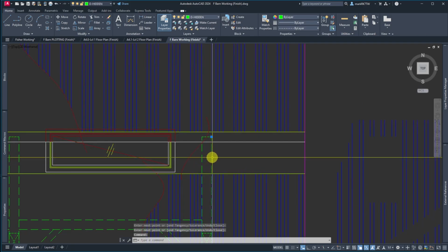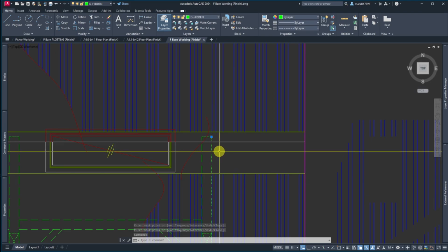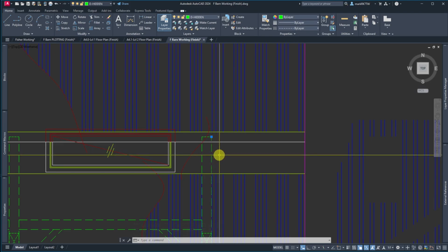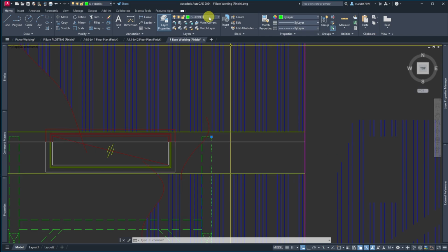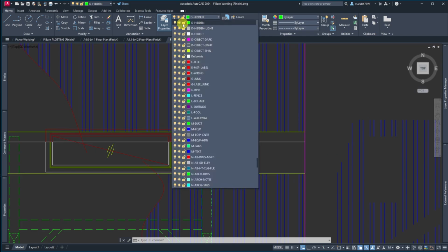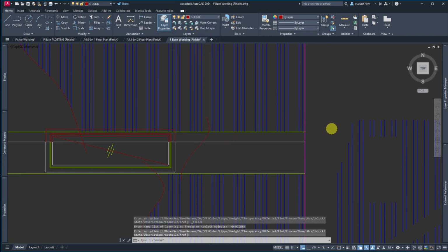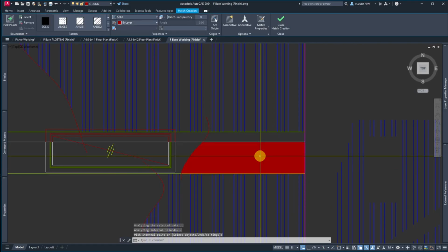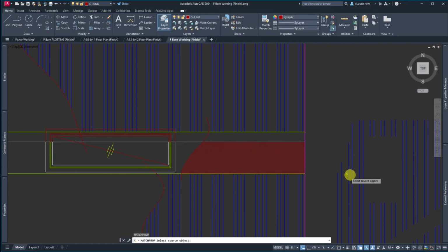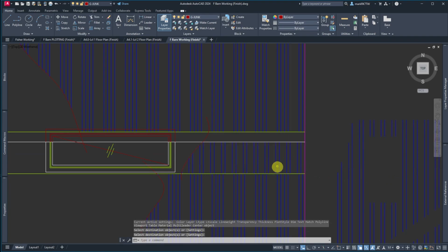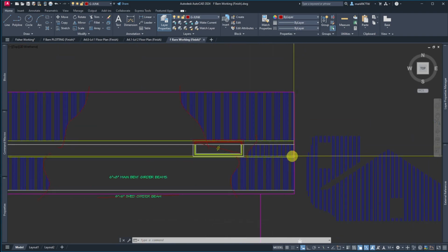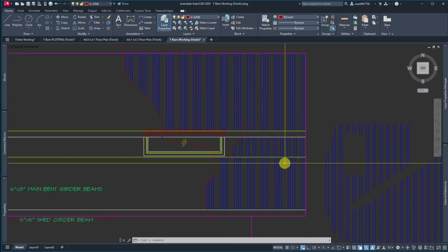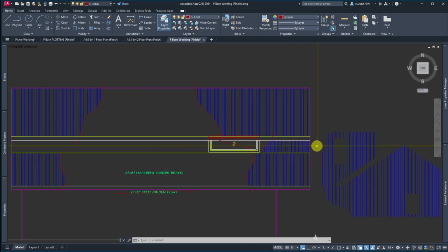That's de-hidden. And if I want to make it the way that I did my other stuff, I would actually change that to that line style. But for right now, just to make this fast, I'm just going to freeze that. Now it's gone. So now I can go hatch in that area, then MA to match my siding style. And now I have siding. Notice it's different than roofing. And they're really similar, but at least they're different. It looks great on the house.